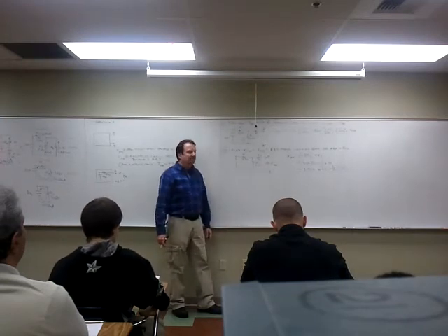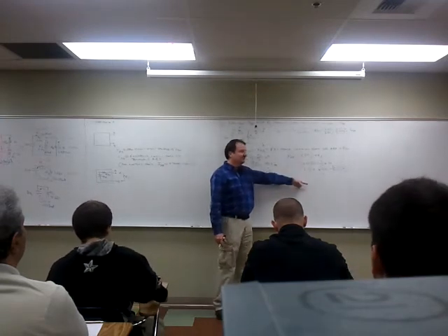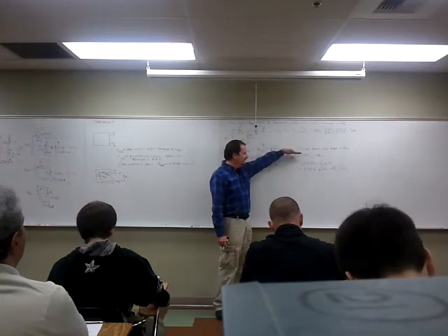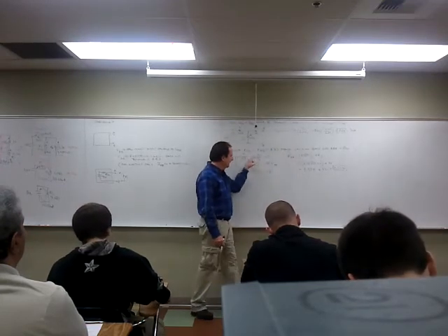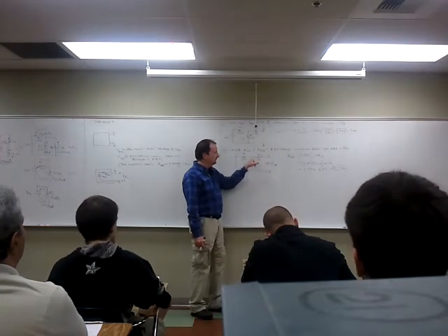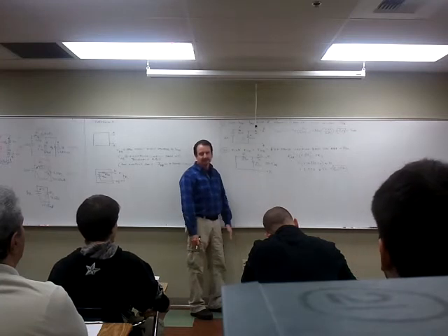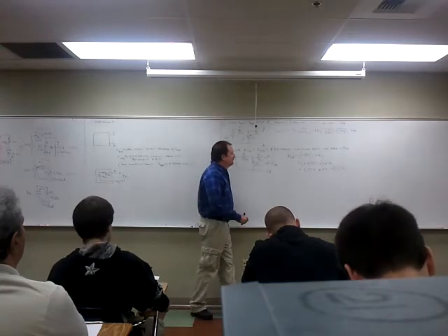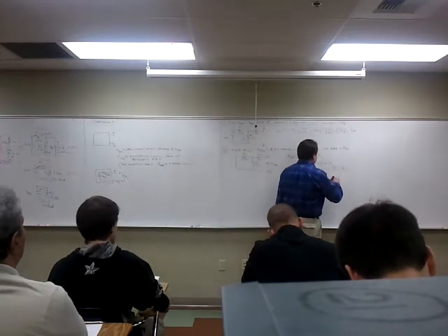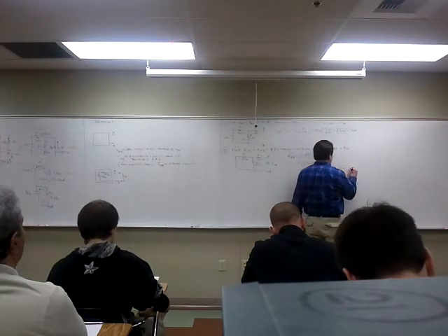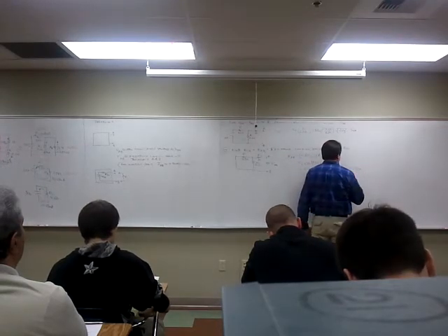Now you're more advanced now. Is it okay that I did this in one step? But couldn't I say step 1 is get R1 in parallel with R2, get RA, then redraw the circuit, it's R3 plus RA, same difference. So that's the resistance looking back into terminals A and B, and that is by definition our Thevenin.